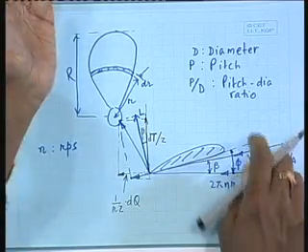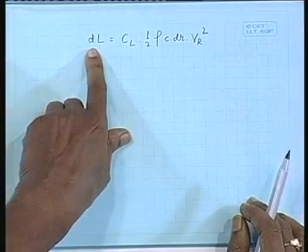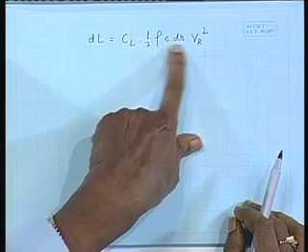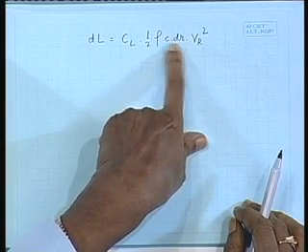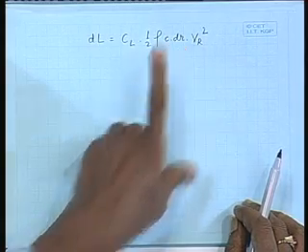Now, if I got this aerofoil data from some tests, maybe in a wind tunnel, then I know what will be the lift for the flow at a particular velocity at angle of attack alpha. So, I can calculate the CL and CD. So, once I know the CL and CD, I can calculate the lift. Remember, this c dr is the elemental area, right?